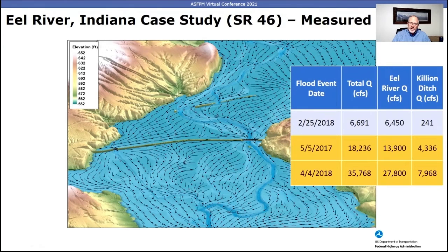But the 2 high flows here span the full width of the floodplain with about 18,000 CFS at one flow and 36,000 at the other. And I might note that for all of these flows, none of them overtop this roadway embankment. Okay, so that's important to note for this analysis. So all of the flow is going through either the main structure or the relief structure. And relative to the 100-year event, which is 48,500 CFS, this high event 36 is roughly 70% of that 100-year flow.